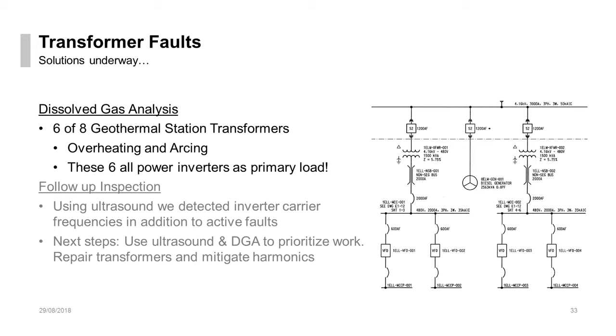Now, when you start talking about waveforms that are not exactly the same, and we know that inverters can cause line-side harmonics, we believe that what may be going on is that we have the addition of these waveforms, which is attacking the insulation inside of our inverters. So in order to test this, we went ahead and used our contact probes, or the stethoscope probe with the ultra probes, and we listened to the inside of our inverters.